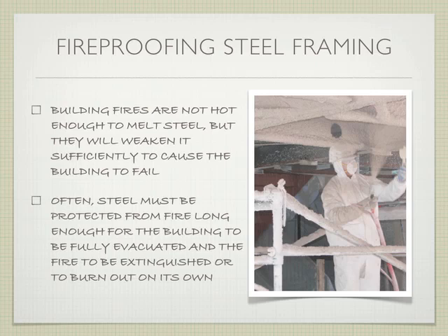So that's one problem. Number two, the building was all steel. It was actually steel trusses that were supporting the building. It was fireproofed in a manner very similar to this, designed to withstand building fires, right, which it should be. The problem was, with the impact, a lot of that got knocked off, right, because it's just clinging onto it. It's not something that's permanently attached to it. It's a spray-on material, right? So we lose a little bit of it. Doesn't mean all of it was gone, right?